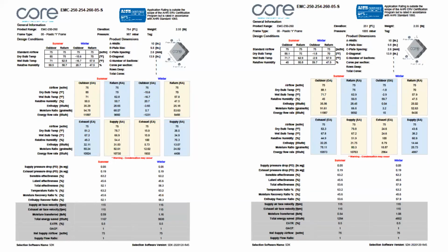And then I had a couple of these core reports run. This will show you, based on the city that you select, what the effectiveness is of the ERV, and gives you all the particulars on the moisture removal and the effectiveness of the ERV. So if there's any requirements for a particular city, I had 4 of them run to try to take a sampling across the Canadian market here. But if there are other more specific ones that anyone would like, we can get those run after the presentation.